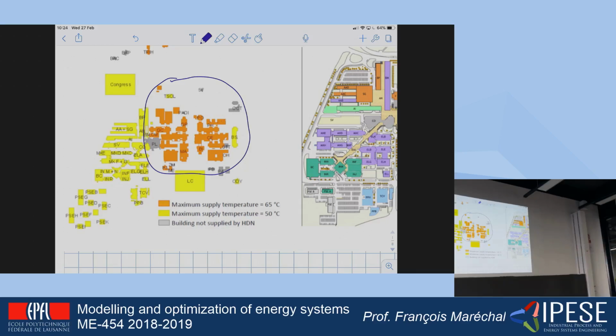So it means that we have two district heating systems. And this is mainly because once they decided to develop the building stock, they realized that the lower the temperature for the heating system, the better is the coefficient of performance of the heat pump. And so if you want to be more efficient, then you have to reduce the temperatures in the building. And so the new part, which is here, in fact, is connected to a lower temperature district heating network.